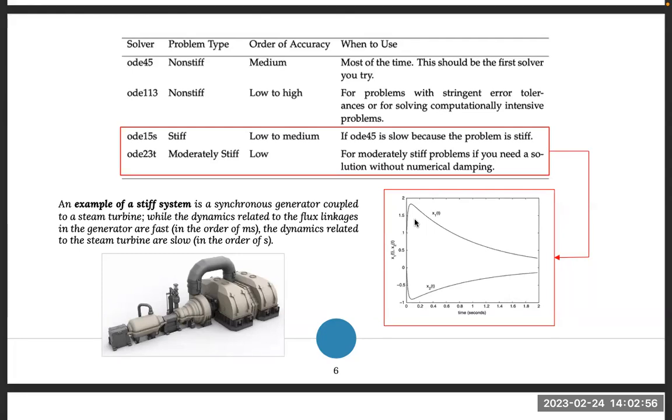So one of the things that you can do if you have a complete model, for example, for the power system, you can say, well, let's focus on the slow dynamics, and let's think that these dynamics are infinitely fast. And you represent those differential equations using something else, what is called a first order manifold.